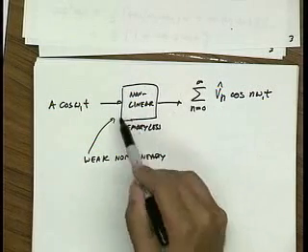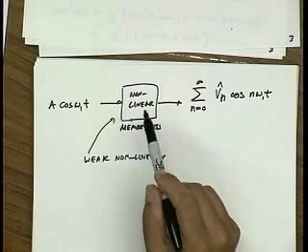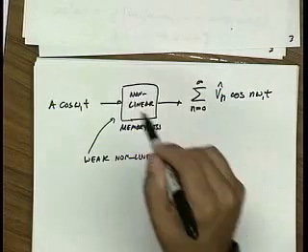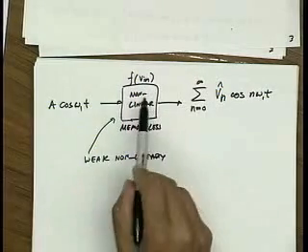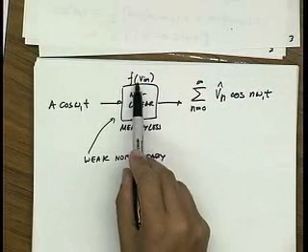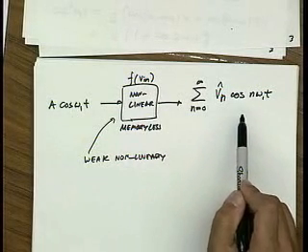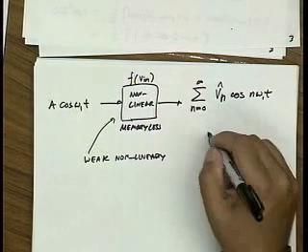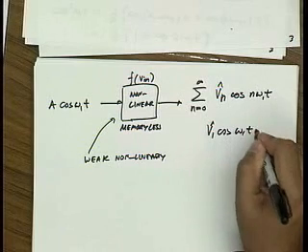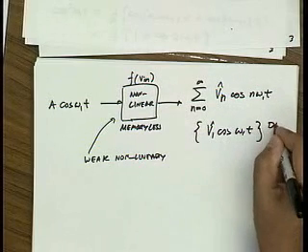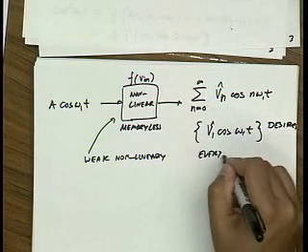But no matter, basically, what we've seen is no matter what's inside this black box, we can represent it as some nonlinear function, right, f of v in, and we do a Taylor series expansion on f of v in, and for a sinusoidal input, it just generates harmonics of the output. So the fundamental v1 cosine omega 1t is the desired tone. Everything else is distortion.